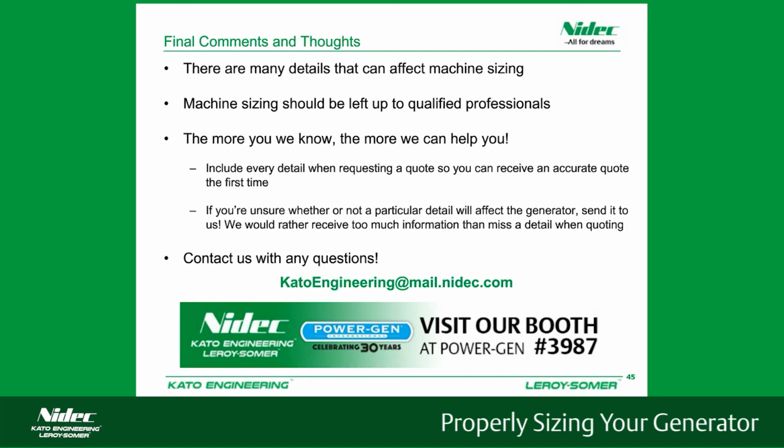So VFDs can be a little bit tricky. I think he's talking about the voltage dip required by it, or possibly the harmonic load from it. The voltage dip from a VFD-driven motor is typically very low because it's soft-started and brought up to speed, so the generator typically doesn't see much in the way of voltage dip. As far as harmonic loading, that's going to depend a lot on what type of VFD you're using. Could be up to 10% derate, perhaps.